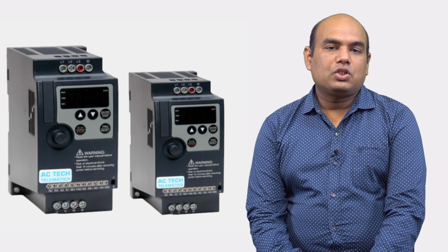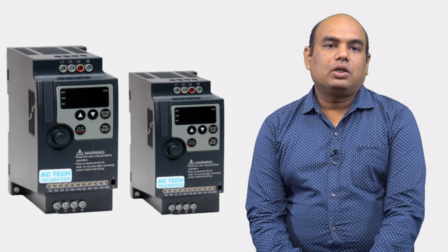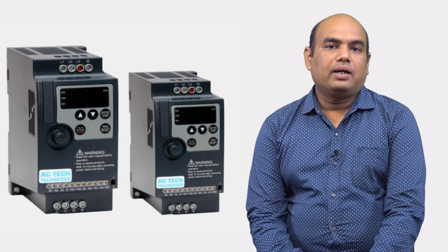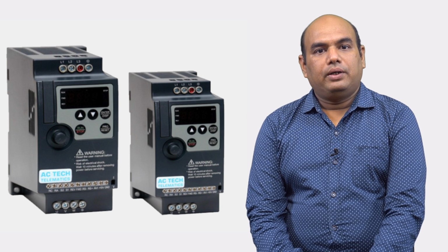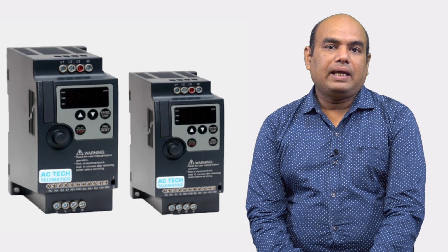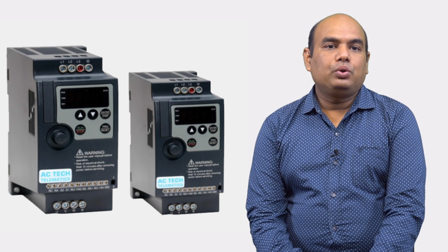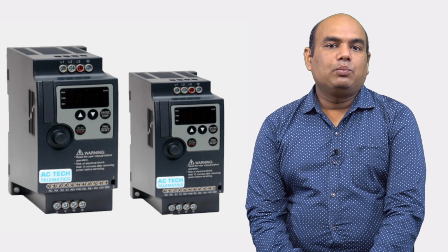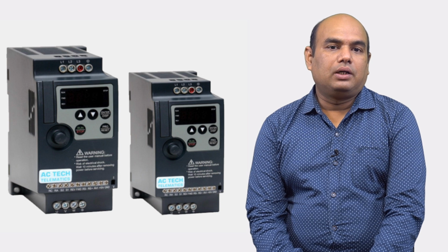When the voltage control is done external to the inverter, the line side rectifier must be a phase control one. By varying the firing angle, the output voltage of the rectifier and hence the input voltage to the inverter can be varied.